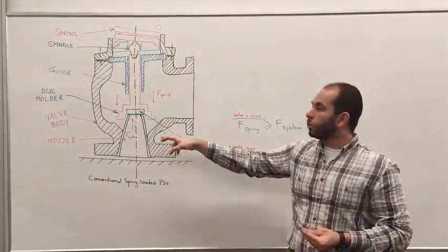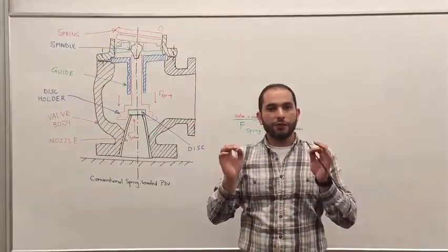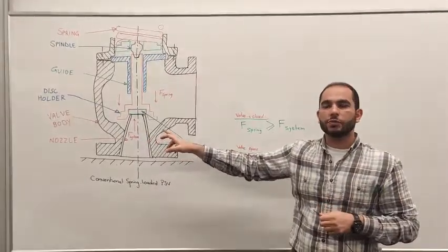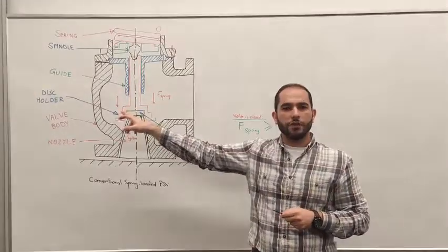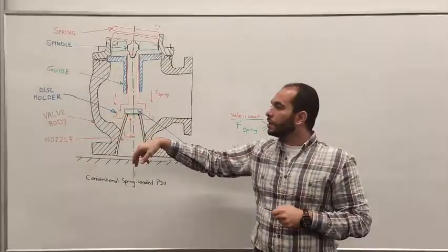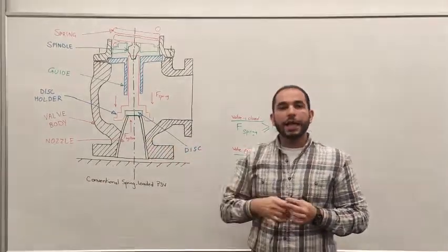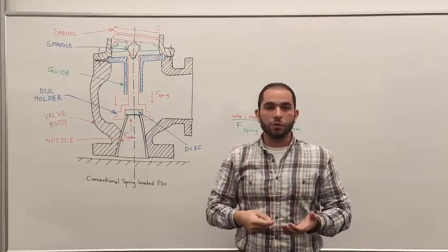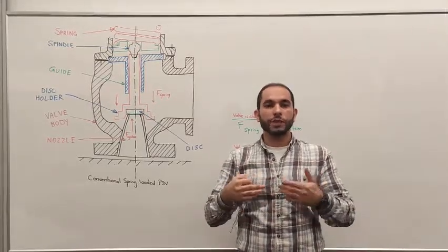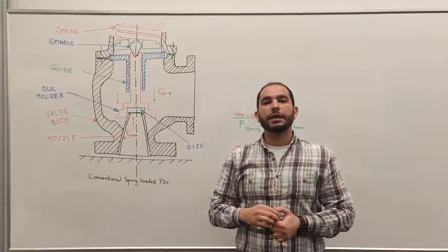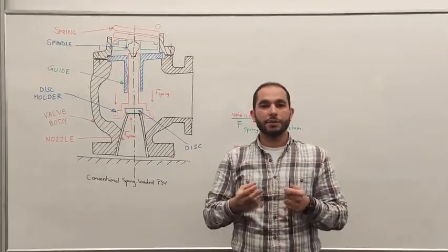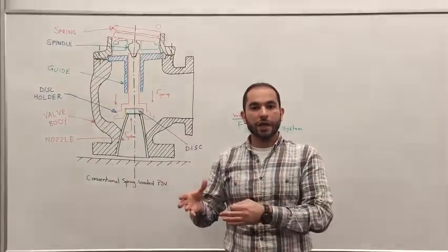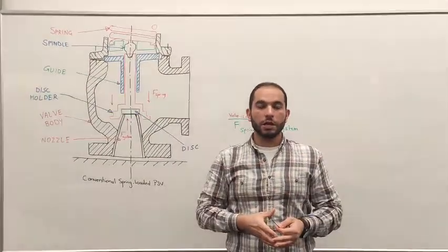Those vibrations, at certain values or conditions, might impair the internal arrangement of the internal parts of the valve. That problem has been experienced by a lot of PSV users, and it has been identified as a major problem causing the deviation of those valves from their original setting point.